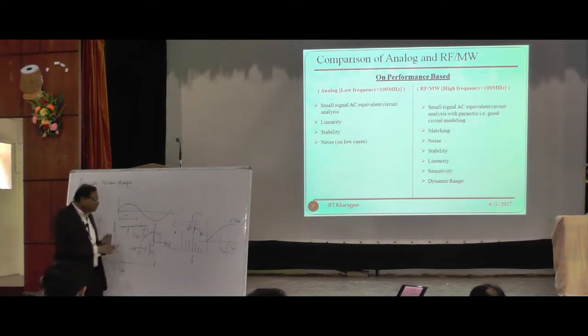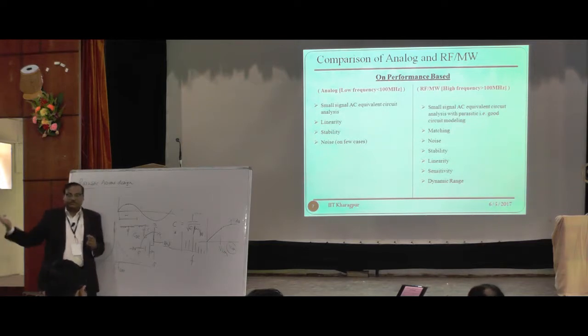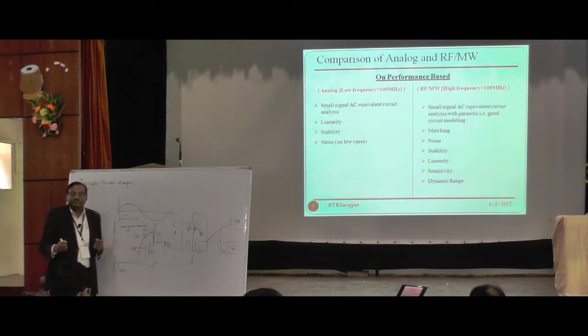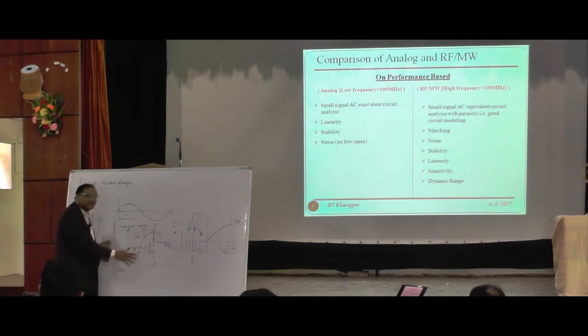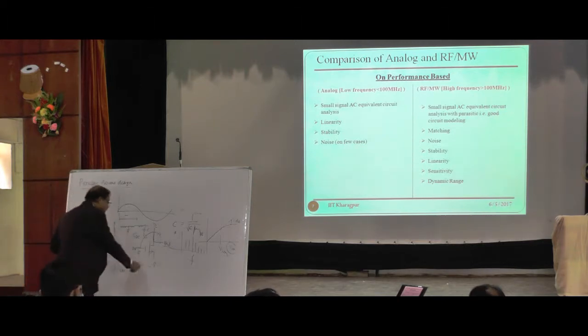You may not know about that parasitic capacitance, but it is a finite capacitance which tells you that some kind of oscillation might occur. Stability means no oscillation, or oscillation with fixed amplitude. In this case, it goes to the unstable state because my amplifier has a fractional output coming back to the input, and that will make the oscillation. Right? It may die down, but again it builds. So this is called stability. Knowingly or unknowingly, you have it through the parasitic path.